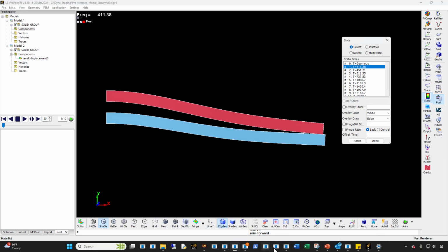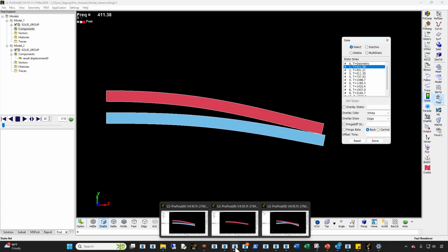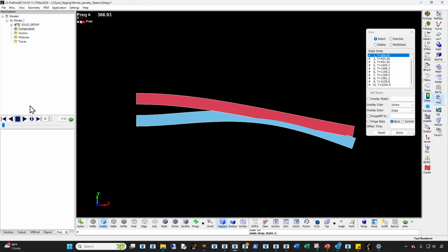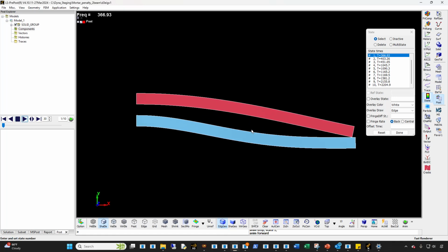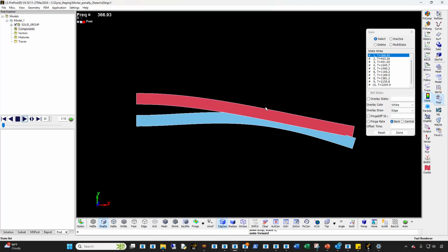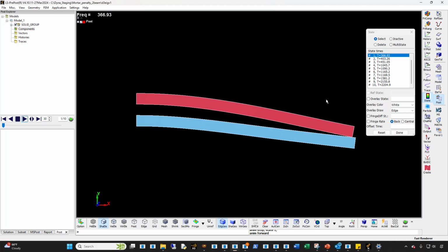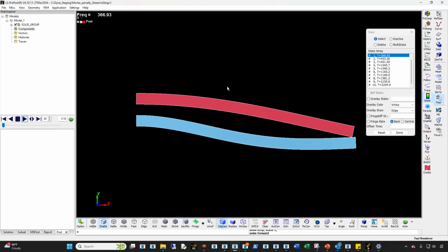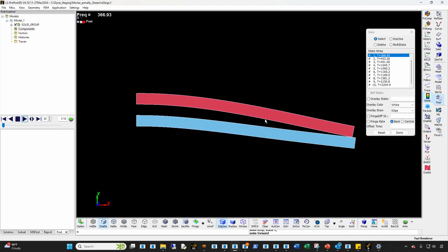But if I were to use the mortar contact, which I got thanks to the recommendation from one guy from Ansys, you can sort of see this now matches much better. This is the first mode of a pre-stress analysis, and this is with a mortar contact. You get a much better matching. You get a mode shape that matches with what mechanical is doing.